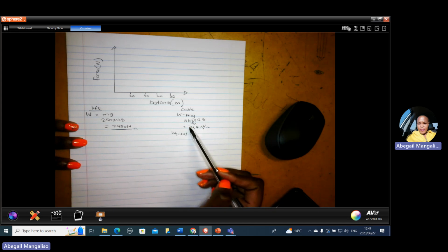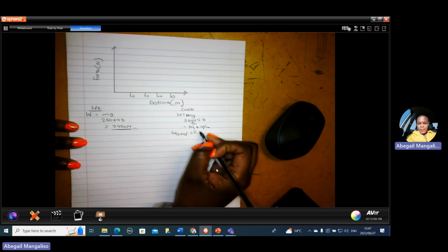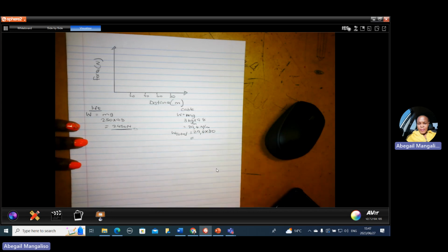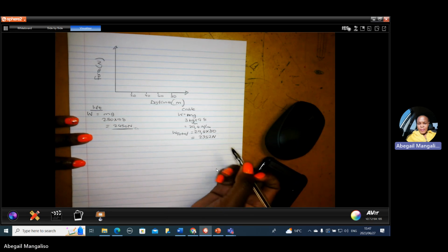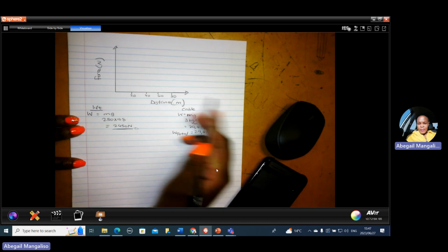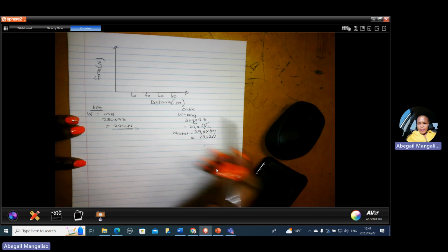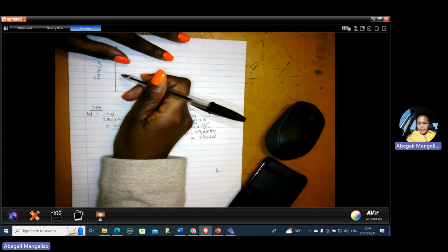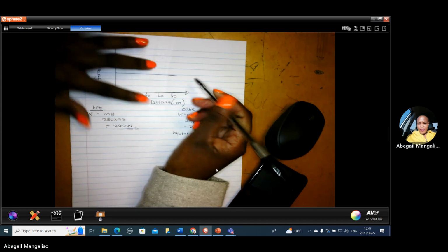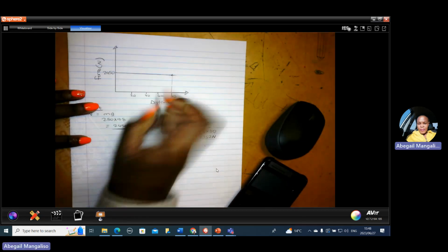But if you want the weight of the cable for the total of 80 meters, you're going to multiply this answer by 80. So it's 29.4 multiplied by 80, which is 2352 newtons. On a single meter, it's 29.4, but over 80 meters, this is the total. The lift's weight is not going to change at any position, so the graph for the lift alone will be constant. It's not changing. So here there is 2450 for the lift alone.